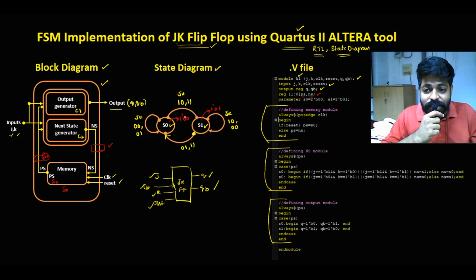So I assign not with 1 bit symbols but with 2 bit symbols. S0 is assigned 2'b00 and S1 is 2'b01. So I use two coins, not one coin. Previously one coin was used, tail for S0 and head for S1, but the same notations repeat for other variables also. So to do the proper assignment I use two coins: tail tail is the indication of S0, and tail head is the indication of S1.